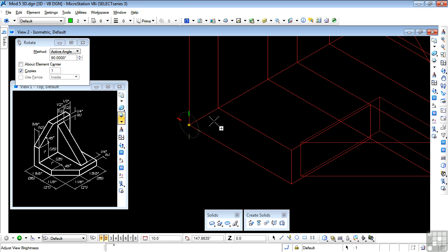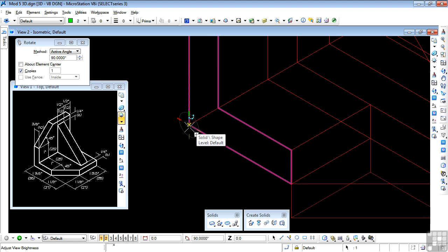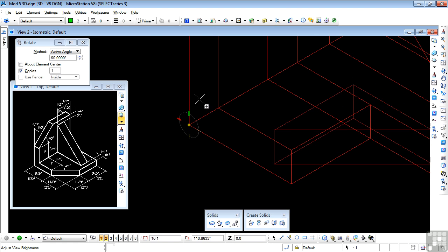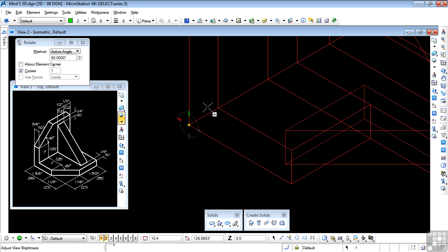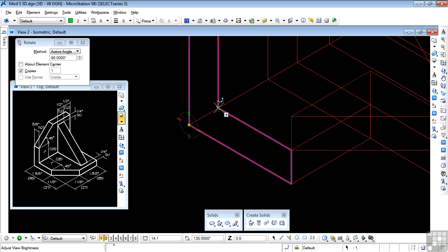In that case, since my compass is there already, I'm working in the plane of this face, which is perfect. All I have to do is place my cursor on that corner, do not data point, and now I use AccuDraw's calculator to divide the distance between the compass and that snap point by 2. On my keyboard, I will use the /, which is the divide operator, and up pops the calculator just above AccuDraw's window at the bottom of the screen. And I divide by 2.